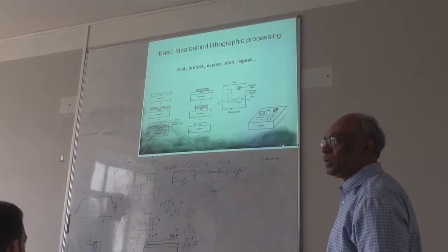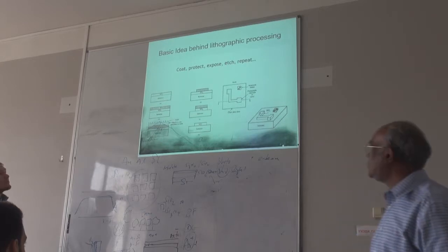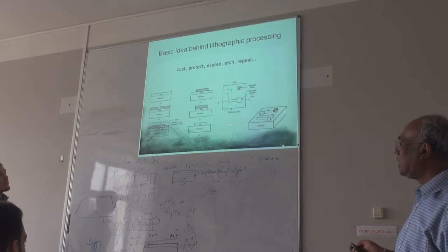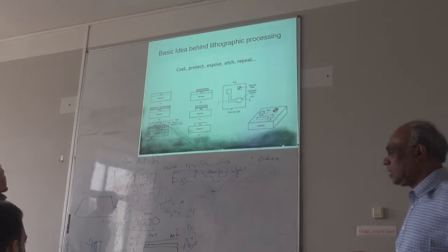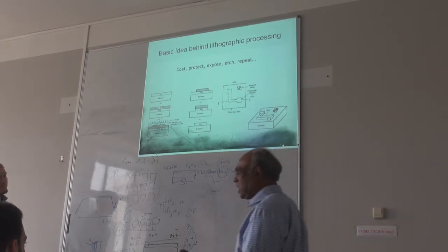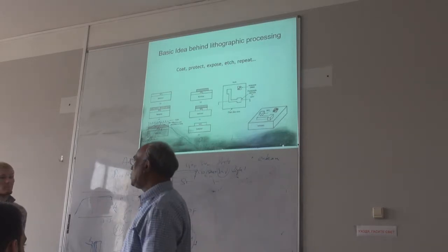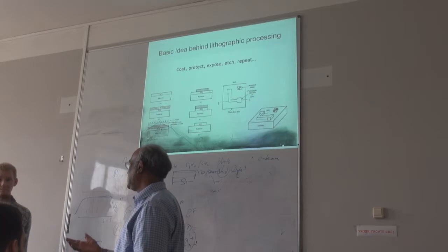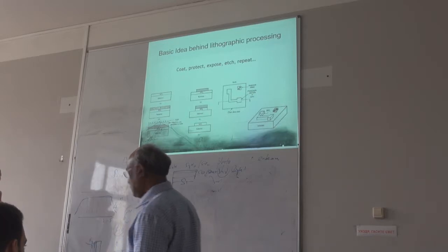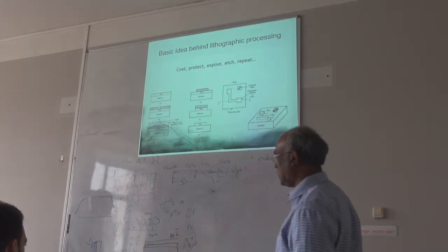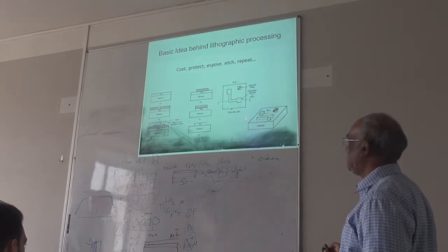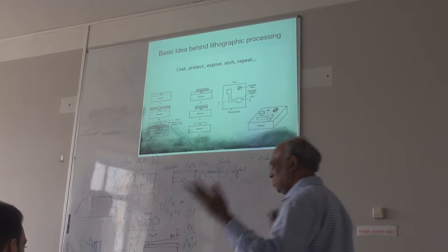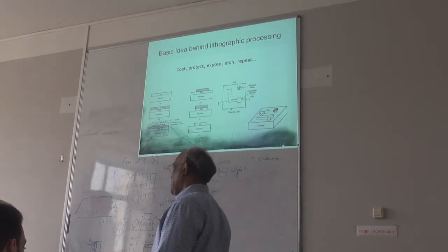So then you have to use photolithography. First, you have to make a mask of that pattern. Usually people don't make masks now. There are a lot of companies; you send them a pattern and they will make it for you, and they are not very expensive. You can make masks in your clean room, but it's much easier this way. We never make masks; there are companies, and in 2 days they send you the mask.